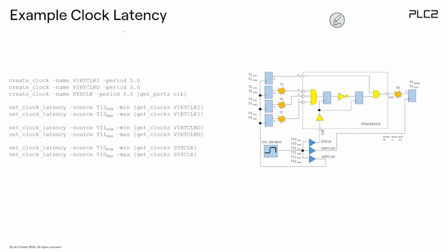Very, very simple case. Again, this is my FPGA. In my FPGA, I have 4 inputs, A, B, C, D. These 4 inputs are connected to 4 external devices, and all of these external devices might be of different type, from different vendors. They have different min and max. This is the timing behavior which is defined in the datasheet.